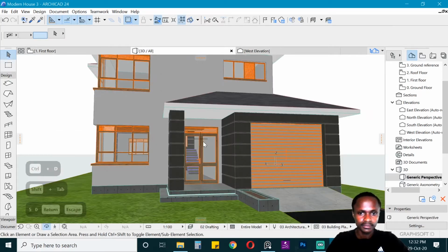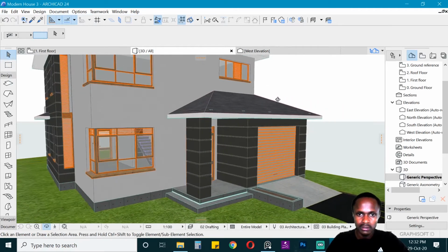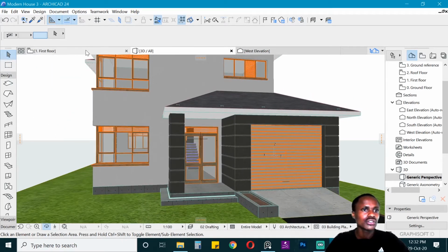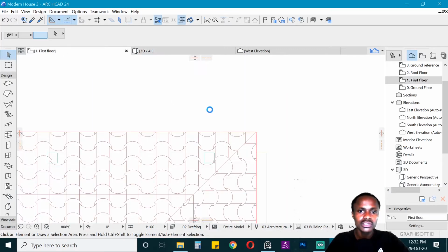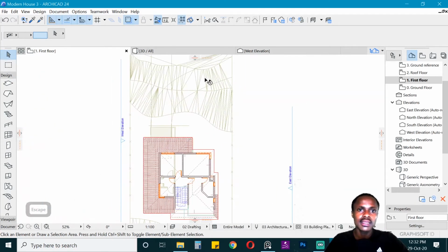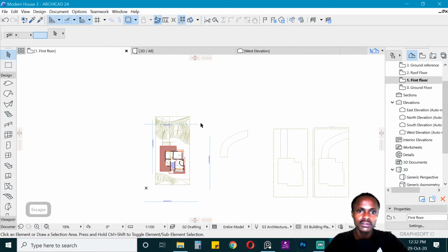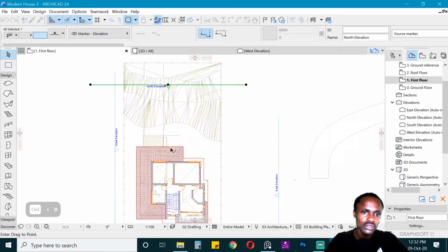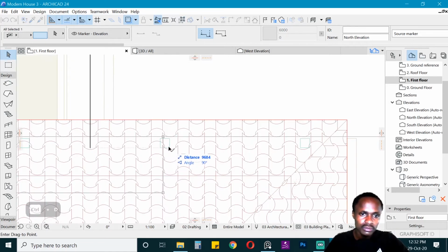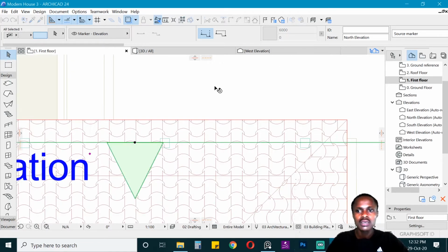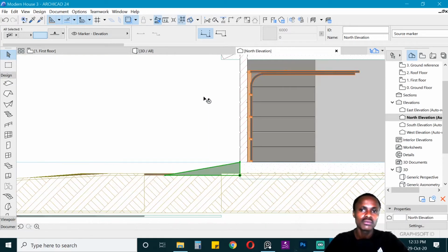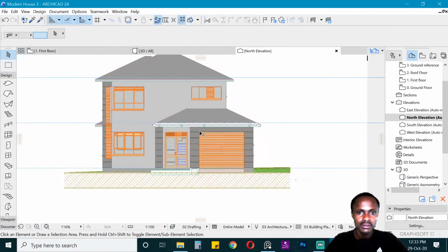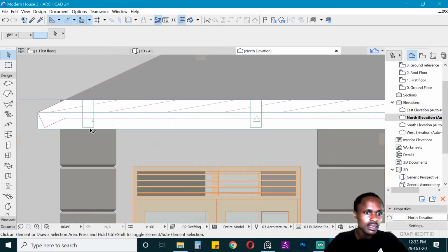Okay, just look at what you have done in 3D before you make some good decisions. Of course, they're not going to show up because we used the wrong slab, which is in a different place. So for us to edit them well, let's get this existing elevation and move it by Ctrl D to the place where we can edit this. Just cut through them. Right click and open with current view settings. Come in here, and yeah, this is how it looks.